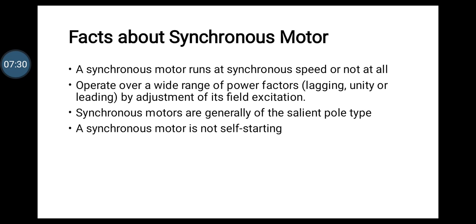Like a single phase induction motor, we need some auxiliary methods to start the machine. And the machine must be run up to speed and synchronized with the supply. That means a synchronizing operation has to be performed. And the fourth one, synchronous motors are generally of the salient pole type.